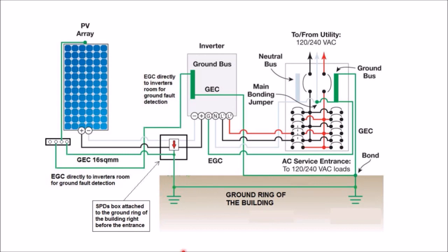Well, and your grounding system has to be continuous too. You can't have multiple ground references, because if you're just connected to ground here, then over here, if you're ground faulting over here, you might be raising the voltage in your ground and therefore making it impossible for the breakers to detect a ground fault. And so your grounding system needs to be continuous. And so here we have the equipment ground conductor connecting all parts.